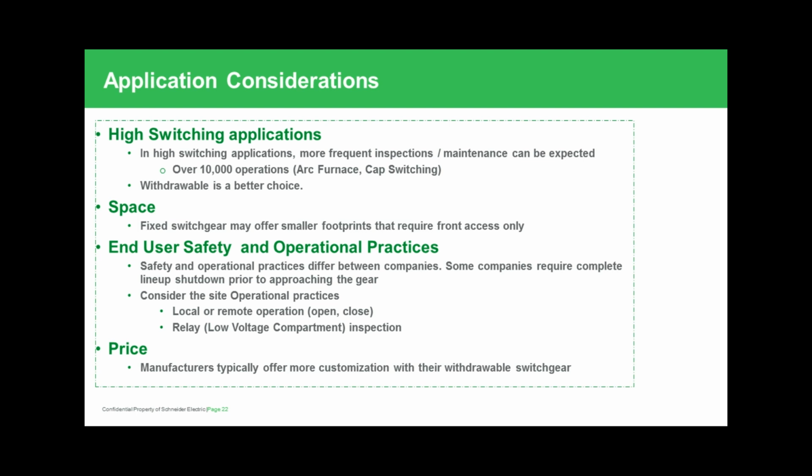Your end user safety and operational practices. What are your safety concerns for your company, for your personnel who work for you? You want to take those into consideration and look at the different techniques that you get with equipment. Does it come in an arc flash option? Can you do arc flash mitigation? Those are different things that you can get with a switchgear. Your protection schemes that you get with it, the size of the relays. Can you have local and remote operation with the equipment? And your shutdown time period that you'll need to consider for your operation.